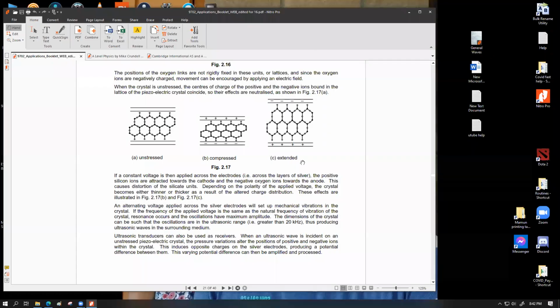For example, an LDR to be used as a part of a fixed circuit. So the variation of resistance can be read as a variation of voltage that happens across it. So it's an electrical information output. Similarly for a thermistor, and here is the piezoelectric transducer, which is also giving out voltage. The reason we are so interested in the output side being electrical information is because we can process the information with electrical circuits. That's how our application capabilities for human beings or researchers have gone through.